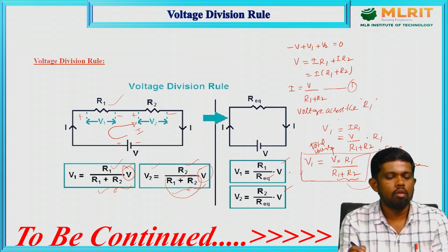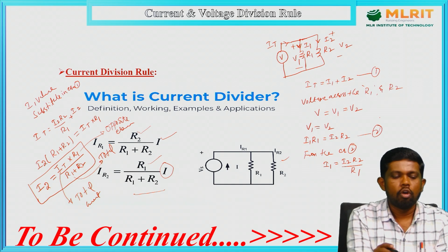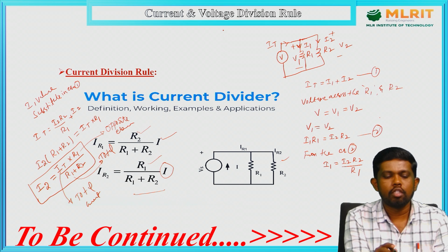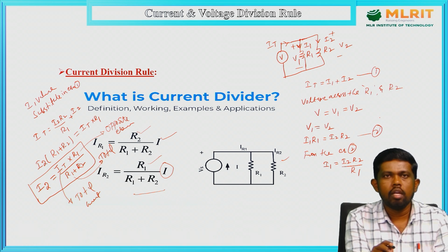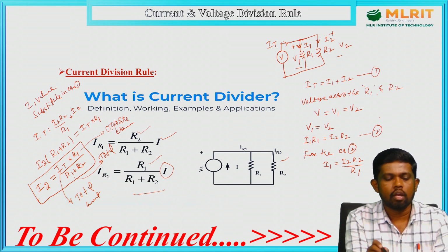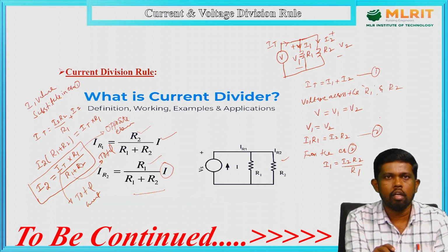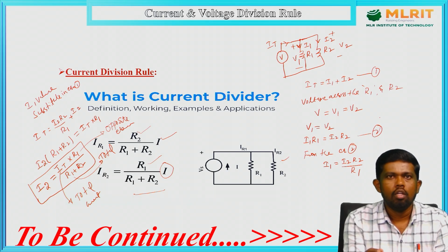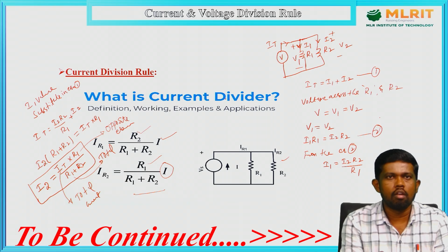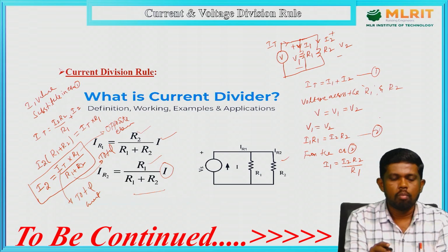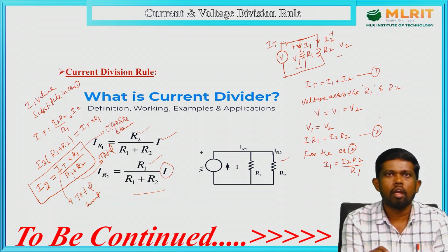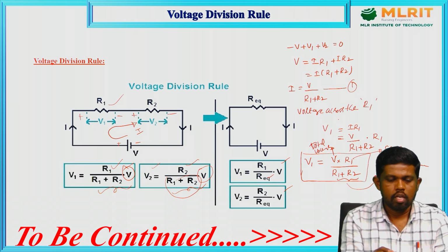To conclude, both are fundamental principles to get the voltage and current values of different circuits. By using the current division rule we can get individual element current values without applying KCL or other Kirchhoff laws. The voltage division rule is likewise a fundamental technique to determine the voltage across individual resistances when they are in series. So these are the voltage and current division rules.